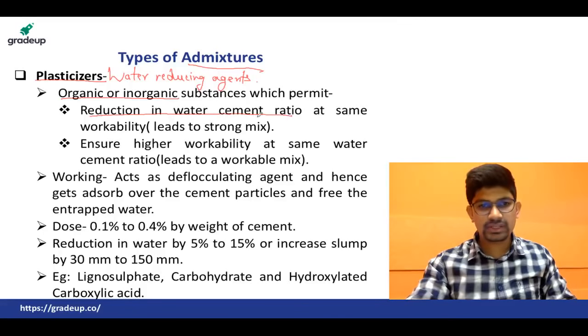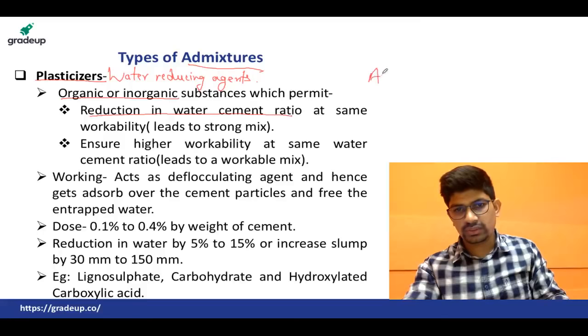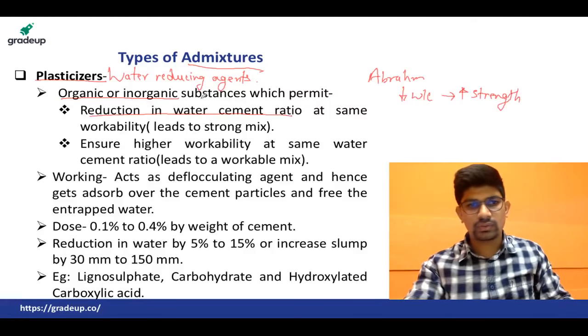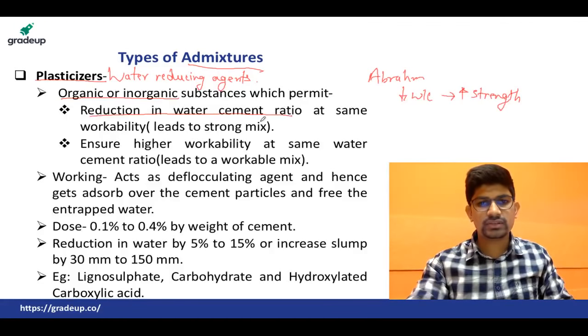Now if water cement ratio is reduced, you know Abraham's law. As water cement ratio decreases, it leads to increased strength. So if you are reducing the water cement ratio at the same workability, you will be getting a strong mix which will have enhanced strength, a greater strength.